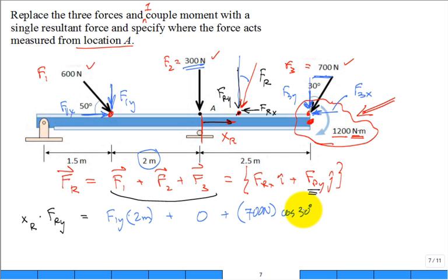And its moment arm distance is 2.5 meters. This one makes it want to rotate counterclockwise, where this one made it want to rotate clockwise. This one made it want to rotate counterclockwise, right? Well, if I'm going to be adding these and subtracting them, let's pick a direction which is going to be my positive. Let's say that this is the positive counterclockwise.